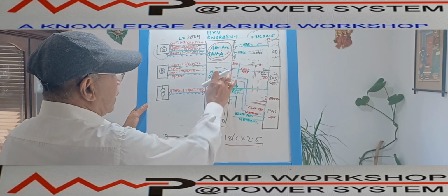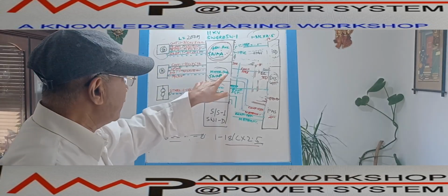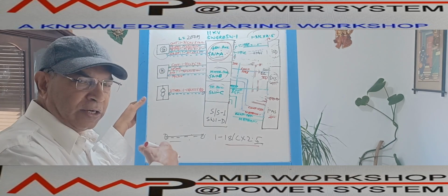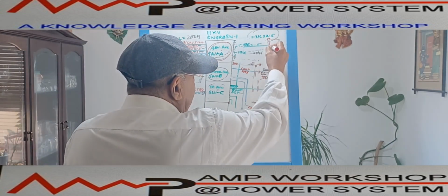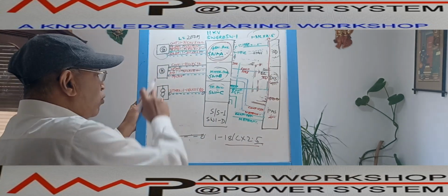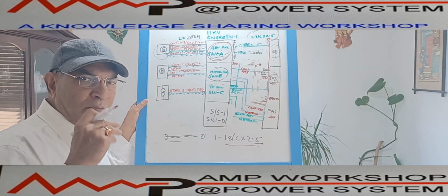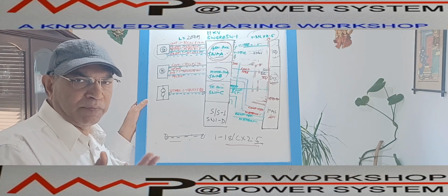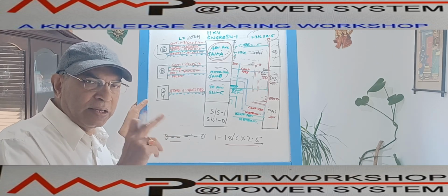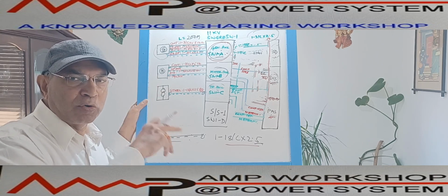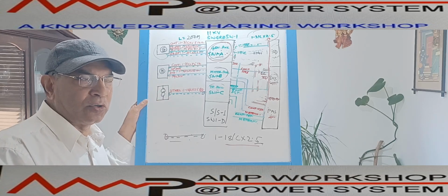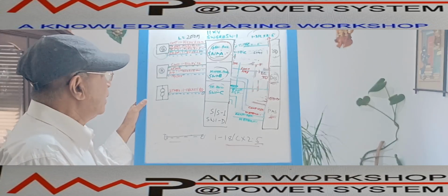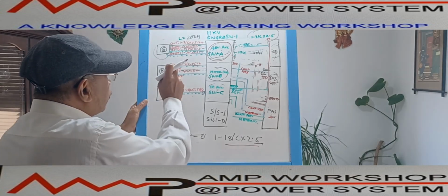Now we come to the motor panel. In the motor, the same way, the motor has a motor switchgear panel, that is panel B. It also has an interface with the motor skid, as well as with all these 3 devices: ESD, DCS and PMS. From the motor skid, why is it connected? The motor is a rotating device, so near the motor, in some cases, motor start and stop we can do from the motor skid itself. So there is a start-stop command coming from the motor push button. So there is a push button station near the motor. In addition to this, sometimes this motor skid has an emergency push button for control purposes. So that is also coming from the motor.